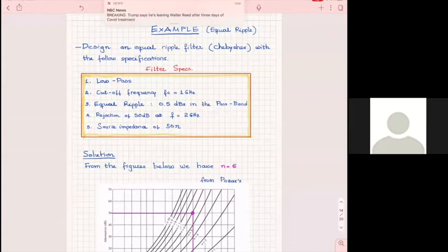There is another application where you have a signal, but you worry most about the spurious frequencies which are very close to your pass band. In that case, I would rather go with a Chebyshev that has very good rejection, and usually your application will tell you how much rejection you will need to have, and it's going to be a spec for your filter.